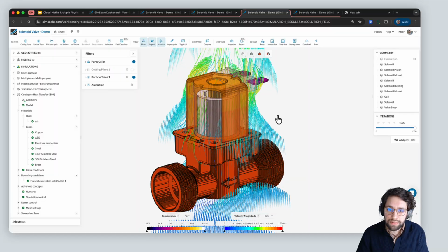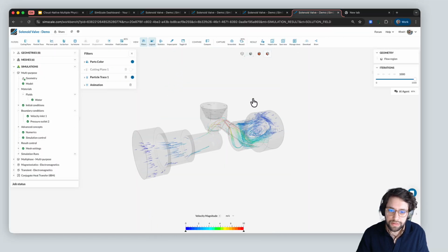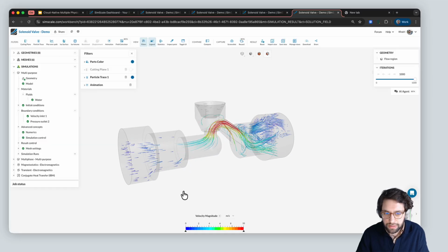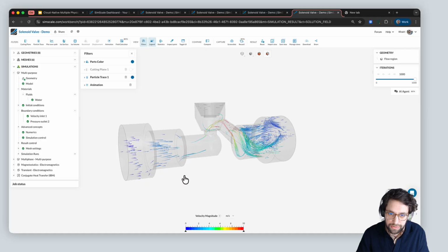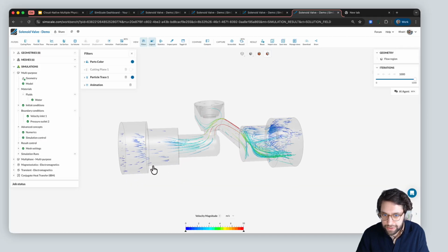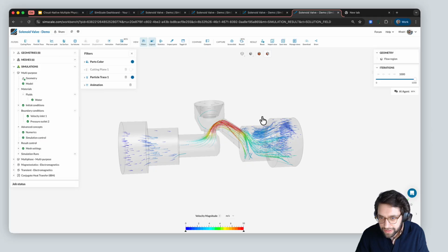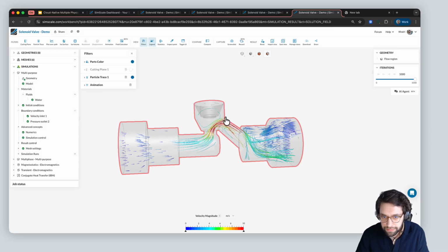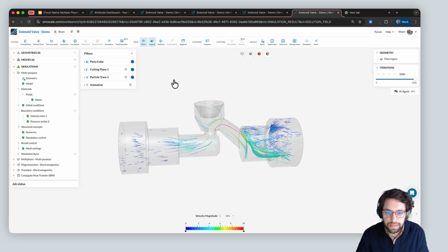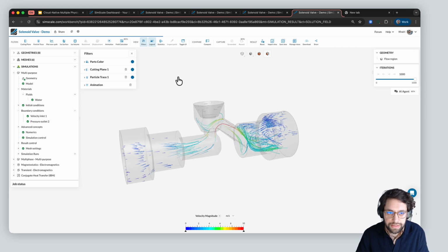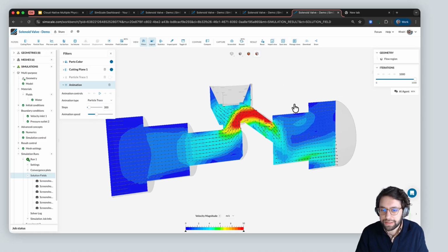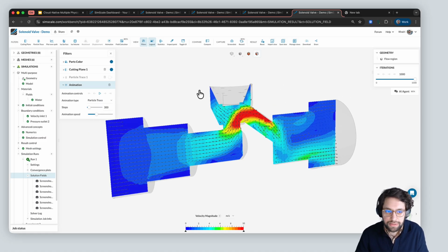Finally, what is also very interesting to look at is, of course, the fluid flow side of things. So for example, here we see the fluid at a particular flow rate, I'm going to talk about that also a little bit later, through the valve body. And we see that this actual design of the valve is actually not really ideal, we are generating a large recirculation area towards the end due to this shooting jet from this side. Actually, this can be also seen quite easily when we look at a cutting plane in the system. We see here essentially our cutting plane, and the vectors indicate really a large recirculation zone happening here. Now, this could be one particular deduction that, for example, this valve body needs to be improved and so on.